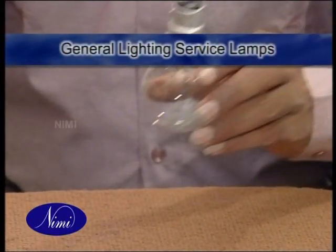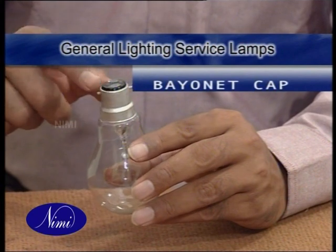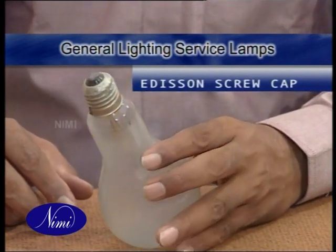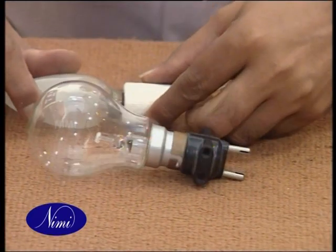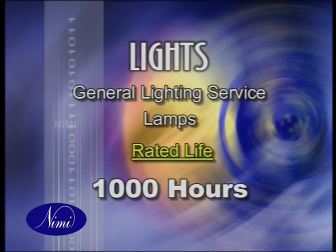The GLS or General Lighting Service filament lamps used at home have a bayonet cap. Some lamps have an Edison screw cap. Edison screws are favored for spotlights, in which lamps must be accurately positioned. Each of them can be fitted in their appropriate holders only. The rated life of a General Lighting Service lamp is about 1000 hours.